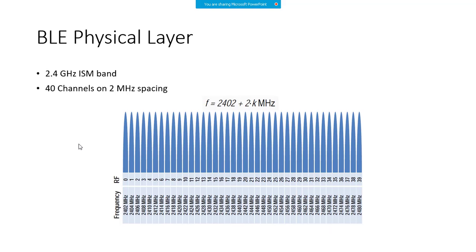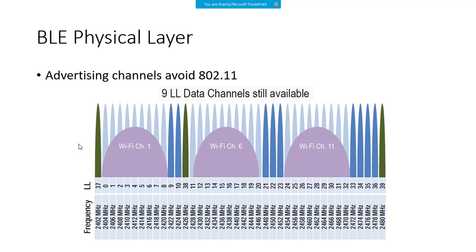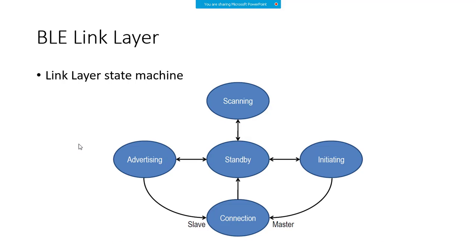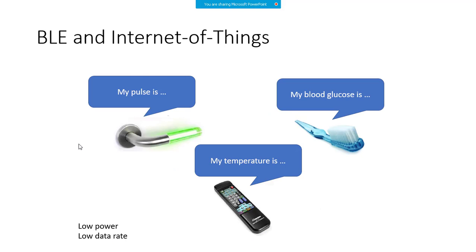And then about BLE, we discussed how you can avoid interference with 802.11, because Bluetooth also operates around 2.4 gigahertz, and Wi-Fi also operates around that. So how can you do so? There are some known overlapping channels, and we are avoiding those, and we have counted. Still, if you avoid all these things, you are getting many channels which can be utilized, including the control and the data channel. So that's what we have discussed, friends, right?